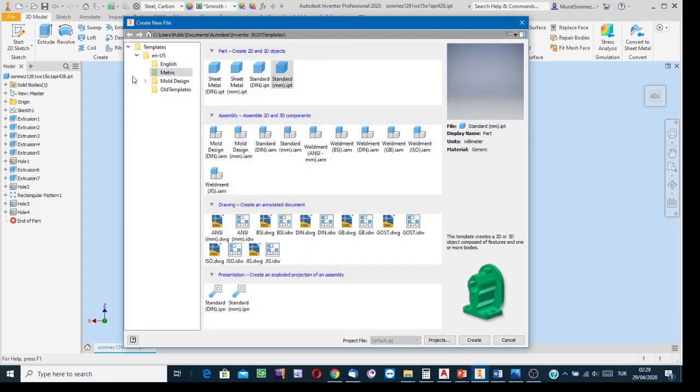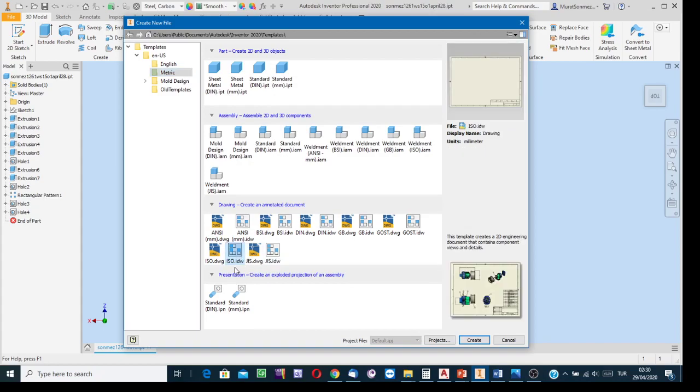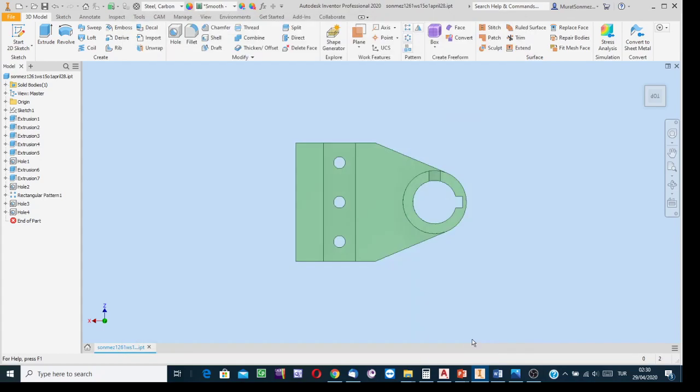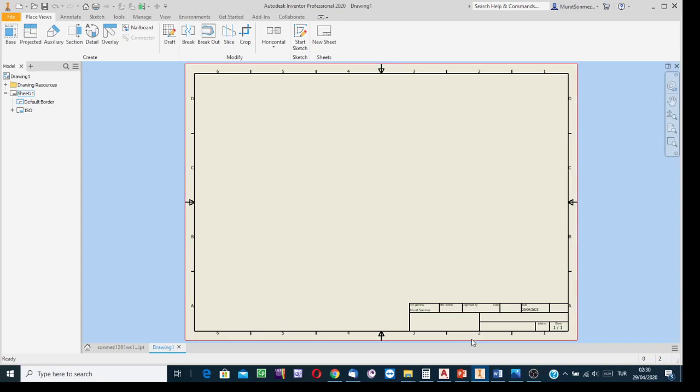First quadrant projection. To say first quadrant, select the metric option, and then from the template option, make the selection of the ISO template option. IDW is the extension. You know the rest. We have A3 size paper. I'm going to have 3 views, and I'm going to check whether A3 is a suitable size to have the images of the object under a certain suitable scale factor.